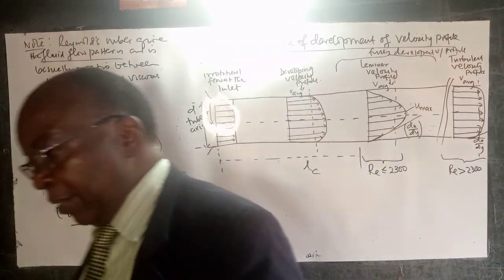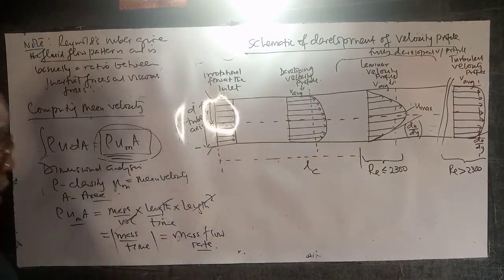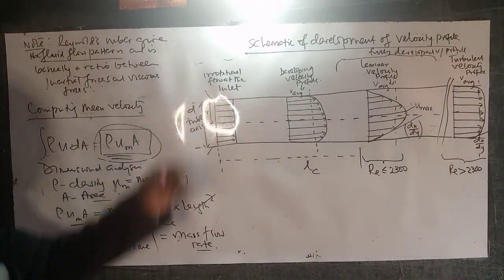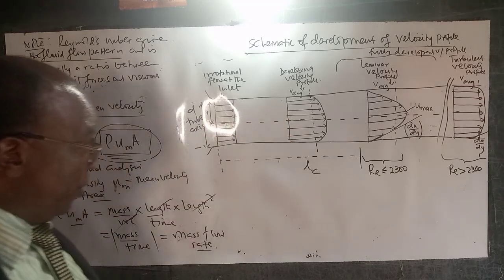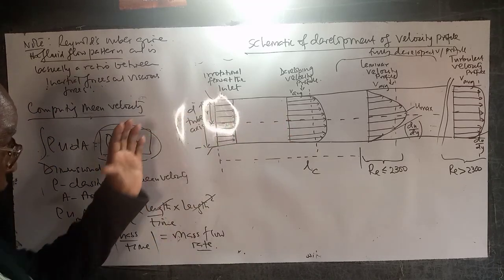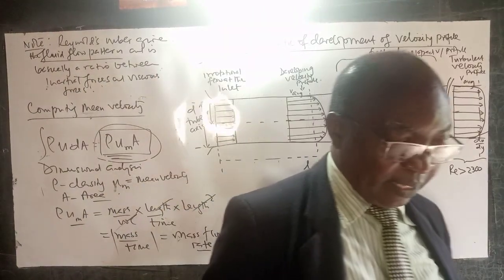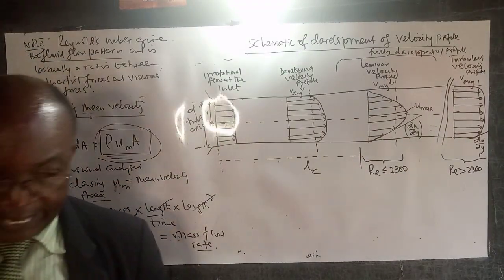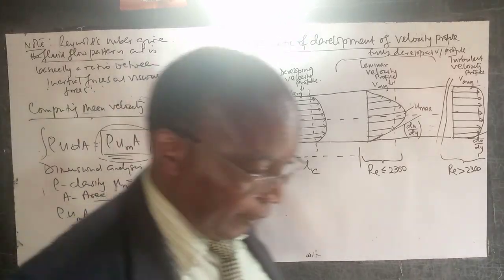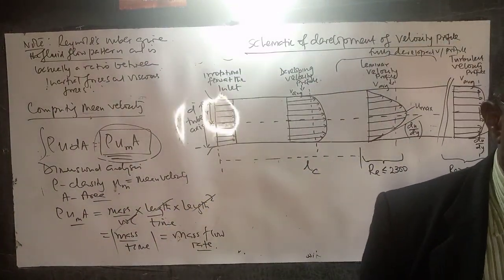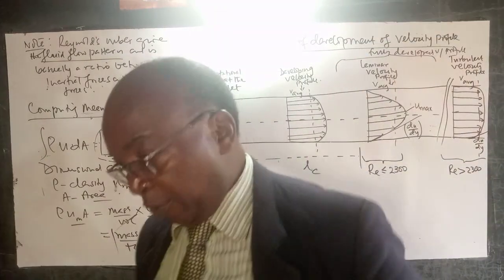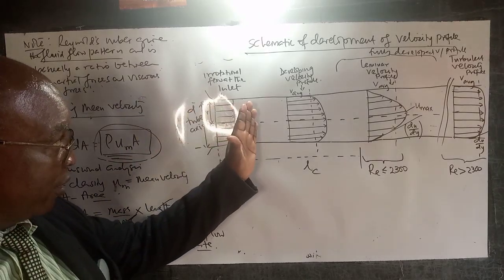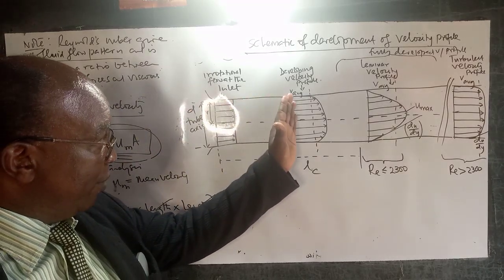So we have seen several important things which we need to mention. One, when we have our fluid flowing through a tube, we're assuming the tube has some diameter D and its radius relative to the axis of flow is r. Now, when the fluid gets in, we're assuming that the elements in the fluid do not rotate at all, the center of mass. So it's an irrotational fluid. But like we have said, if there is significant torque applied from the shear forces at the walls, then of course there will be rotation. Otherwise, as the fluid progressively moves on, the profile will be developing.